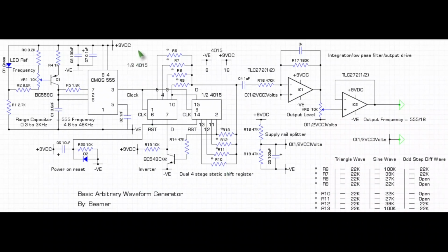no high frequency component interference on the supply line here. If you go to one of those little inverter boards, there is a high frequency component on the 9 volts, and you might have to include a little inductor, resistive dropper or whatever, to filter out those high frequency components.